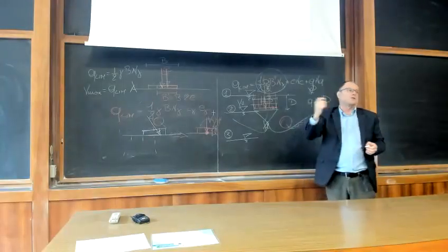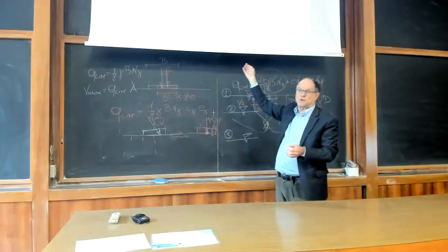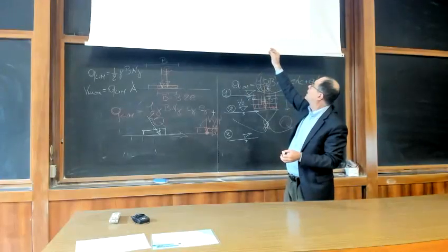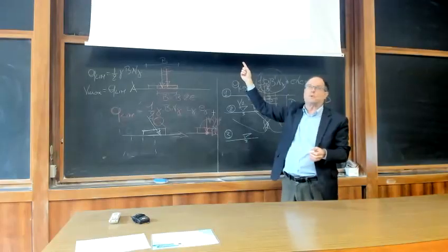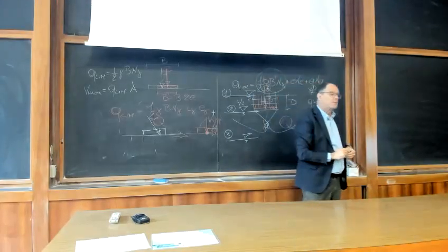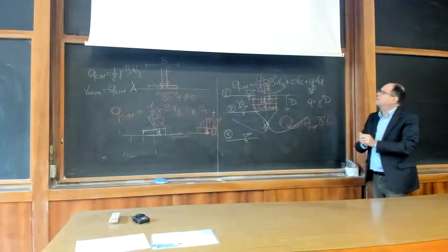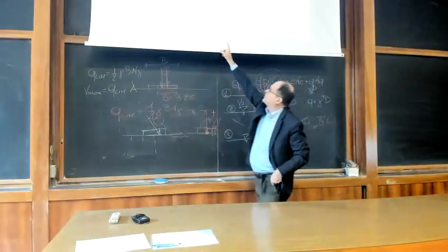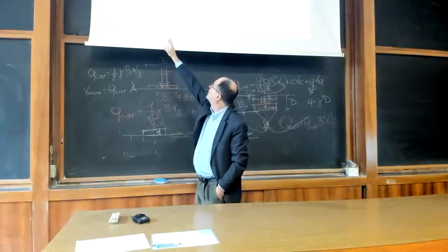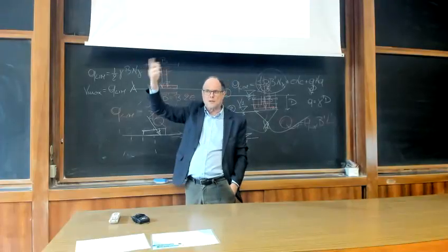So I had plotted just as a qualitative terms. Now you have an analytical expression of the interaction between the two components provided by Brinch Hansen's expression. And as you can see, you have an initial tangent of this expression that is 10 over 7, which is greater than 1.